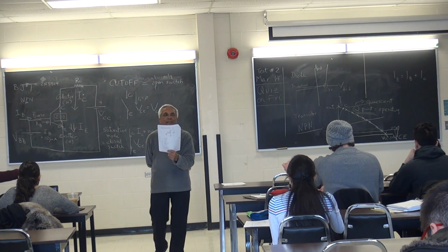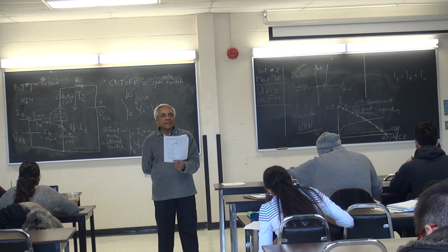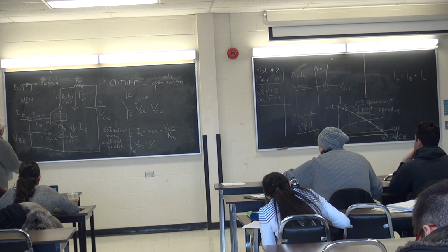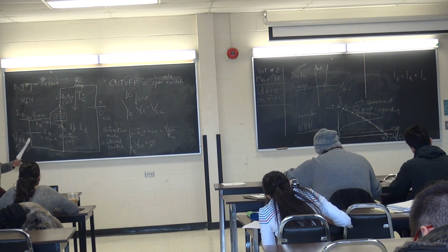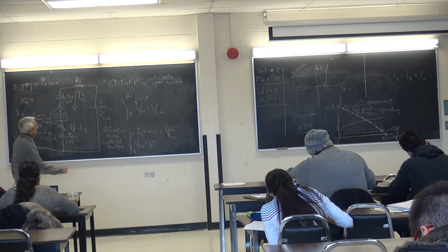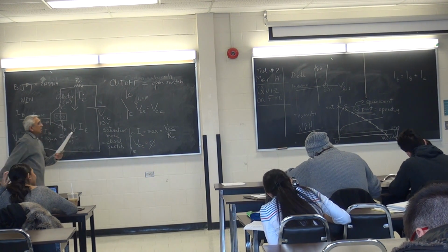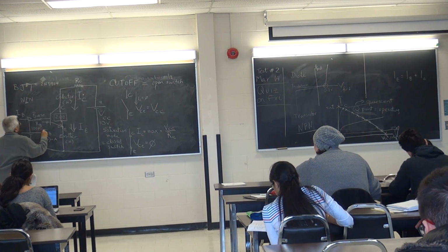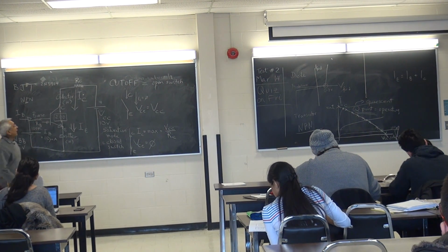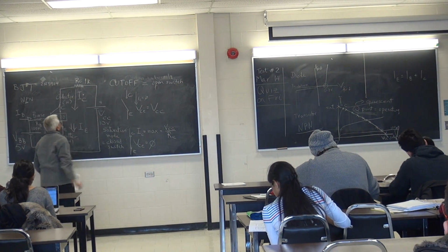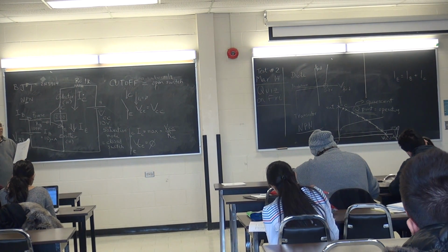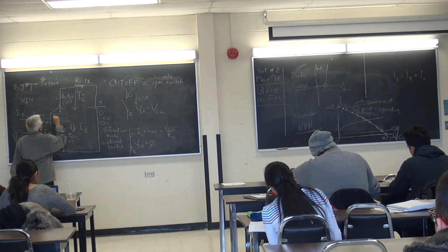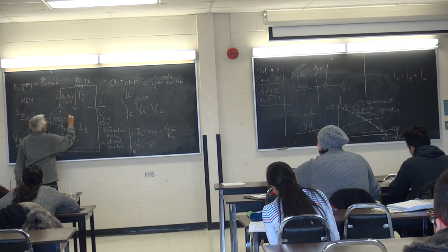So let's go to the top of page 11. In an NPN transistor circuit, like the one we have here, VBB, 5 volts. VCC, 10 volts. RB, 100K. RC, 1K. And the last thing is HFE. This gain of the transistor, HFE, is given to be 150.